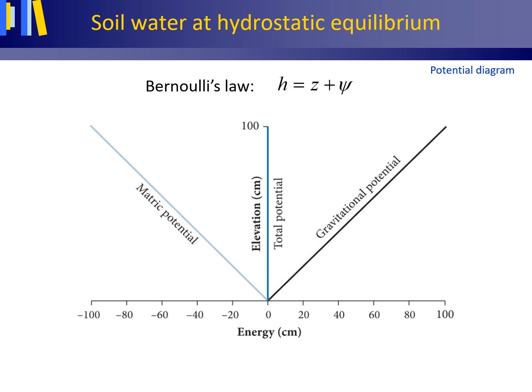Because pores in the unsaturated zone usually contain air, the total energy or total potential cannot be as easily determined as under the water table in the saturated zone, where it may simply be determined as the hydraulic head in a piezometer. In part because of this, a different term is used, namely the total potential or hydraulic potential. From an energy point of view, this term is fully equivalent to the term hydraulic head as used in the saturated zone. Also, for the elevation head and pressure head, other terms are used in the unsaturated zone.